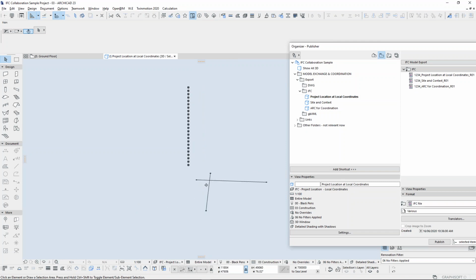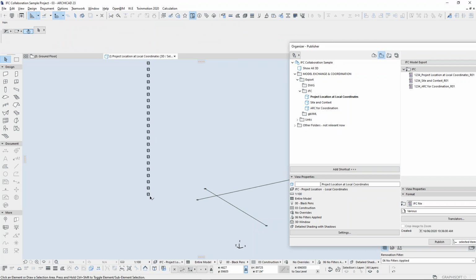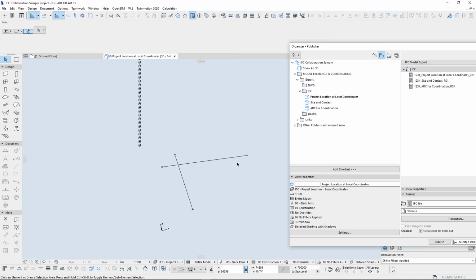Additionally, just because it's a relatively good practice now that not everyone is up to speed with handling their software in a particularly good way, we have also included these cubes or cuboids that are aligned with the origin location of our georeference point. Basically, that will be the IFC 0 for every story. We have also included these 2 grid lines just to make sure that everyone has the building in the same place. That typically is good practice and can be updated as the project continues.